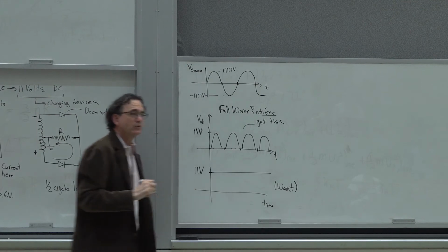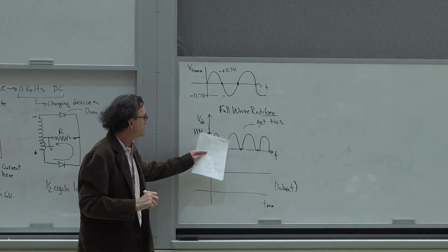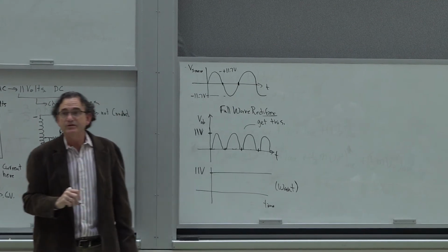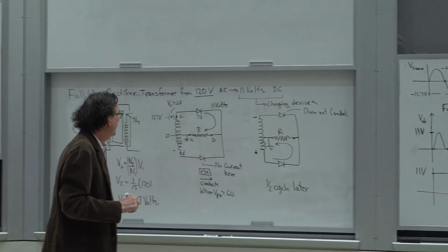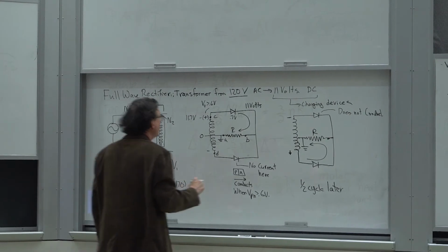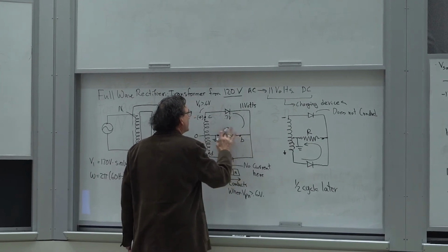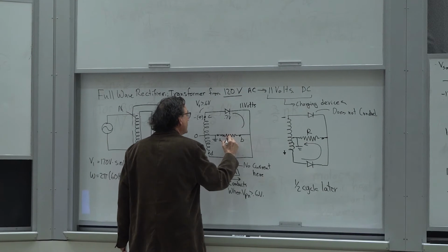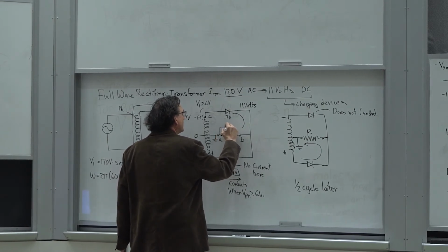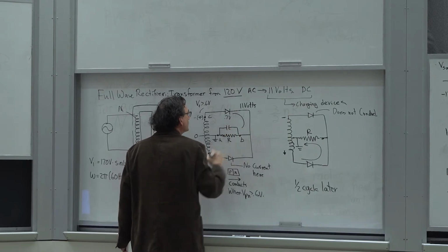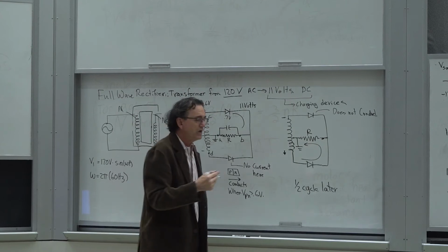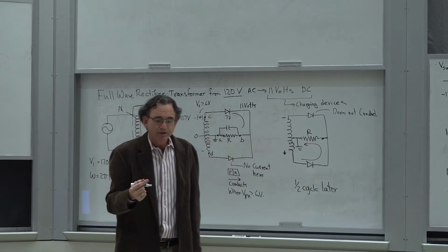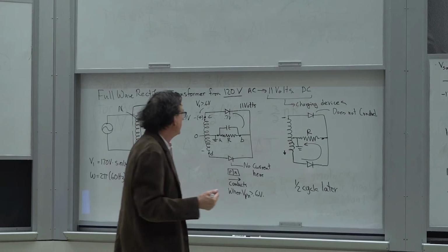Okay? So how do we transform this sine wave into this constant voltage? Well, the answer is that we apply a standard circuits trick that basically says that if I put a capacitor in parallel with this resistor, it will smooth out the ripple. And we're not going to go through the derivation on this. There were some practice problems in 273 that you should have worked with.